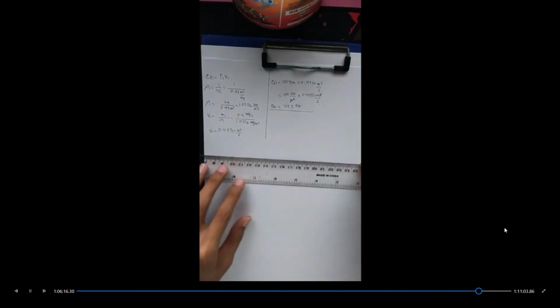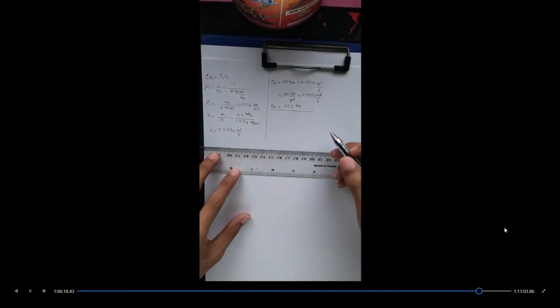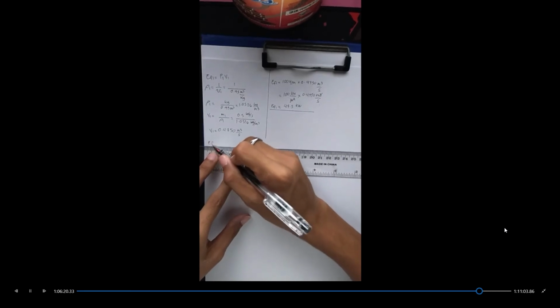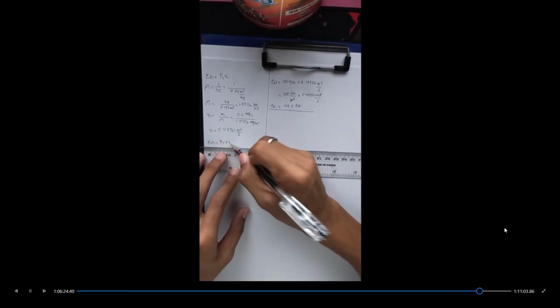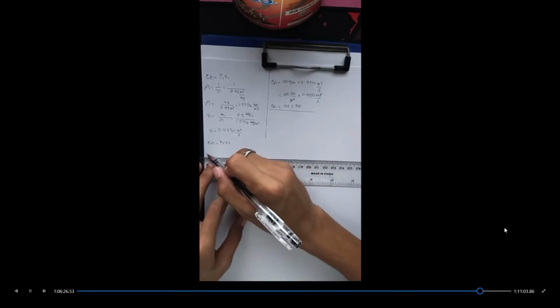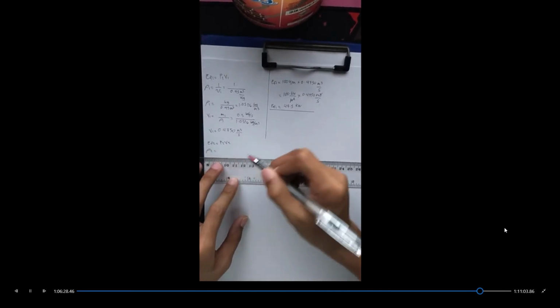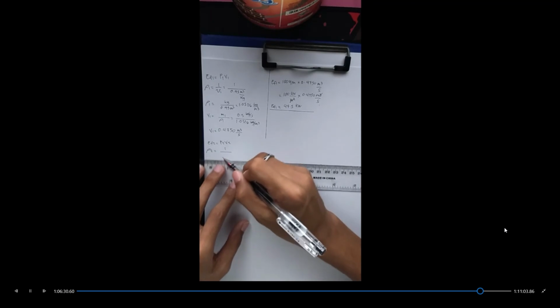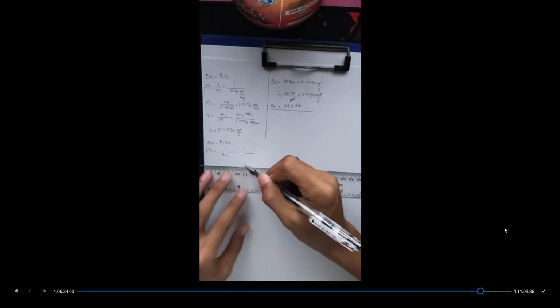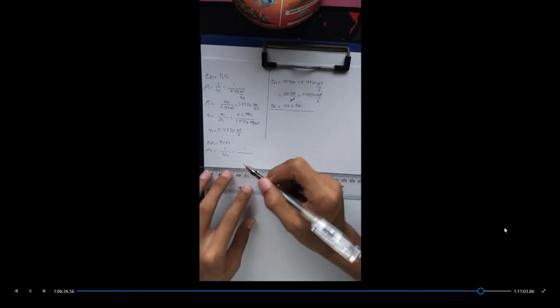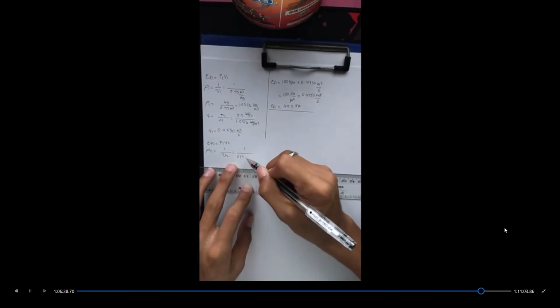That's for flow work 1, and now I'm solving for flow work 2 the same way I solved flow work 1. So pressure 2, volume 2. To solve for volume 2, we need our density 2. Density 2 is the reciprocal of our specific volume 2, which is 1 all over 0.19 meter cube per kilogram.